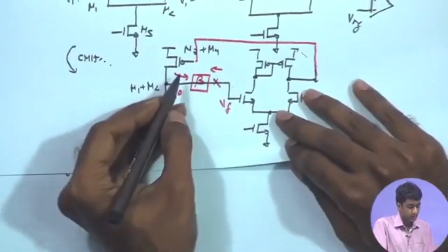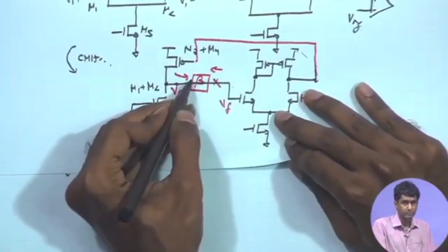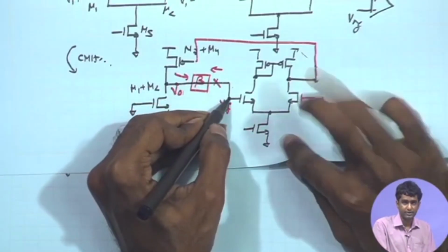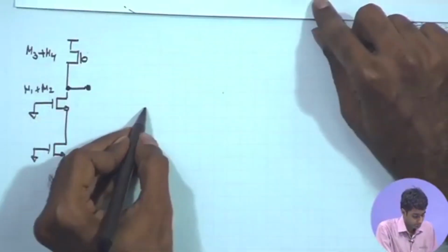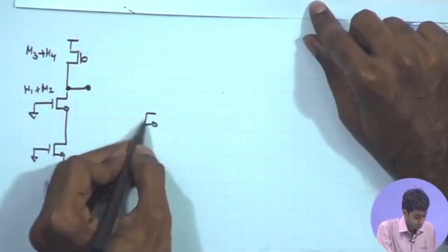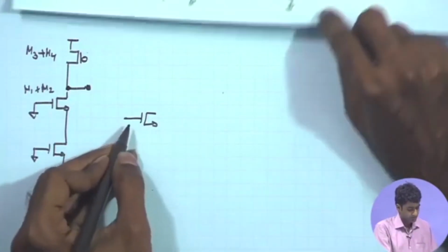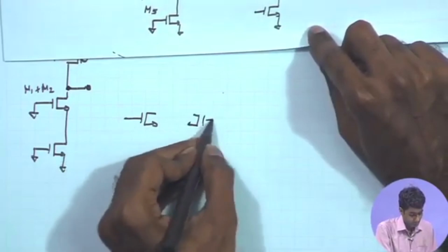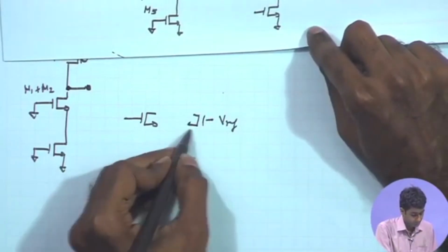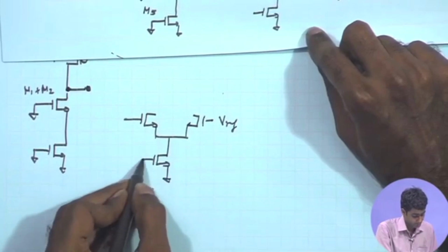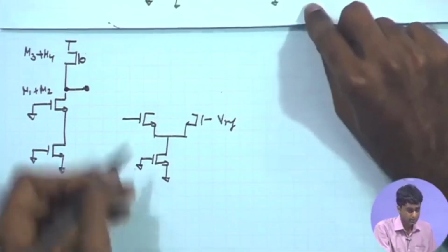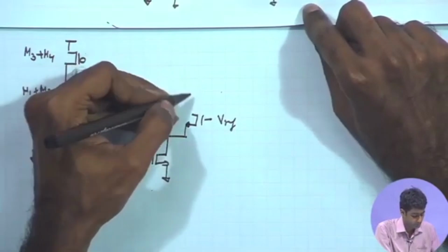So, as we said, looking into the input port of the feedback network, the other end is a series connection. As a result, we open circuit it. So, we are left with an open circuit over here, and on the other side we have the Vref, which we are assuming as the input signal, and the bias point, all the DC connections, DC bias point set to AC ground.